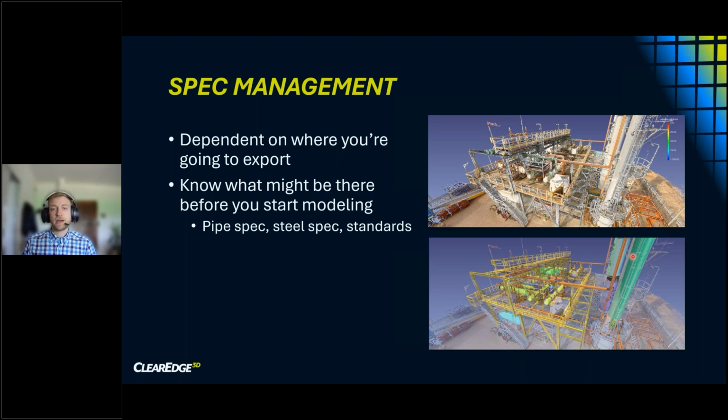For structure, we do have a really nice workflow for E3D, which is that you can export your steel standards directly from E3D, and then in EdgeWise, there's a tool now that can read those CSV files that you created with E3D and natively generate an EdgeWise steel standard that you model with. That contains all the metadata needed so that when you export to E3D, it passes right back through. So it's a nice circular approach. We're looking at applying that in other ways as well, but it's all spreadsheets, and a lot of it is built into the existing workflow and the standard install with EdgeWise.